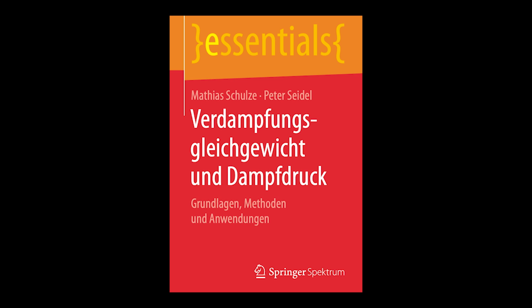Wait, univariant. That's a bit of jargon. Break that down for us. What does that actually mean for the stability of the system? It's a good question. It means the system has only one degree of freedom. Think about boiling water at sea level. We know the pressure is fixed at 1 atmosphere and the temperature is fixed at 100 degrees Celsius. If you try to change the temperature up to, say, 101 degrees, the liquid immediately vanishes. You just move into the single-phase gas domain.